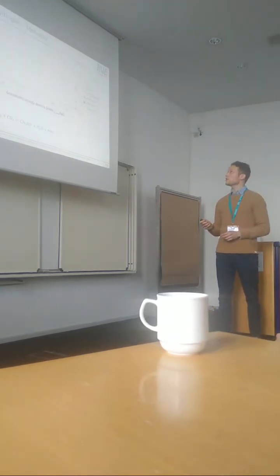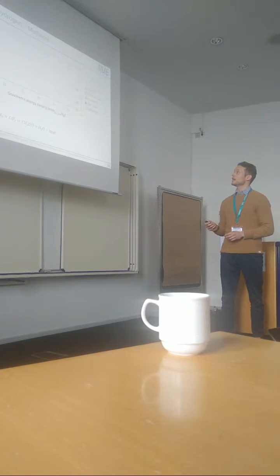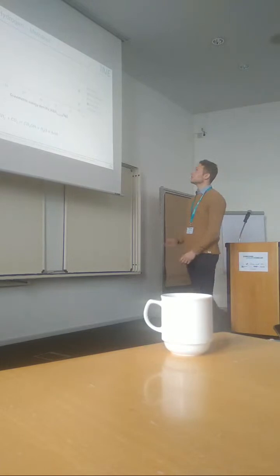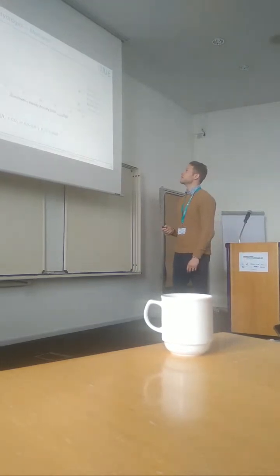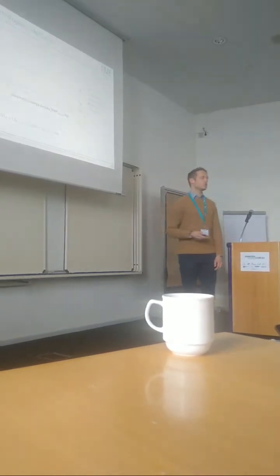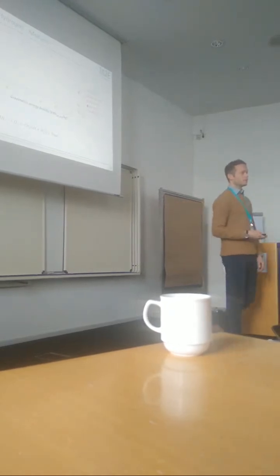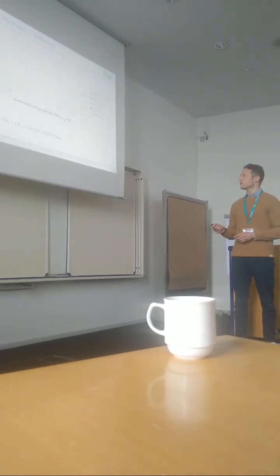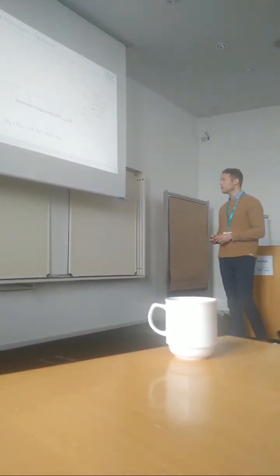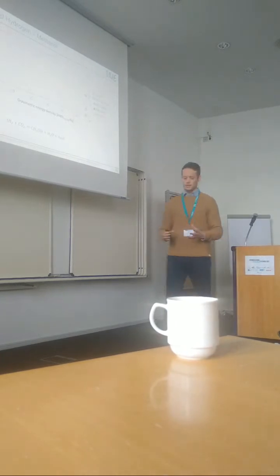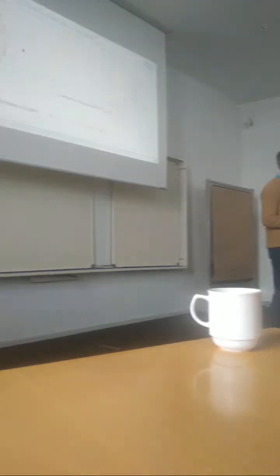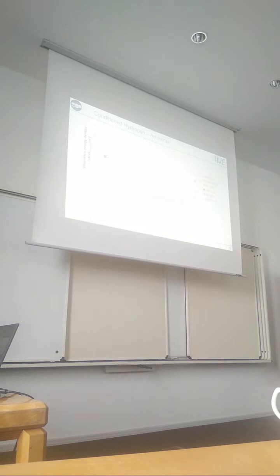Also for methanol, we can see that the volumetric energy density of the hydrogen bound in the methanol is very, very high. So far the highest, and it can also easily be shipped in the existing infrastructure because we already do it nowadays. And also for methanol, very important, we need heat to crack the methanol into hydrogen and CO2 again, and it's the same as for the LOHCs. Now, last but not least, is ammonia.